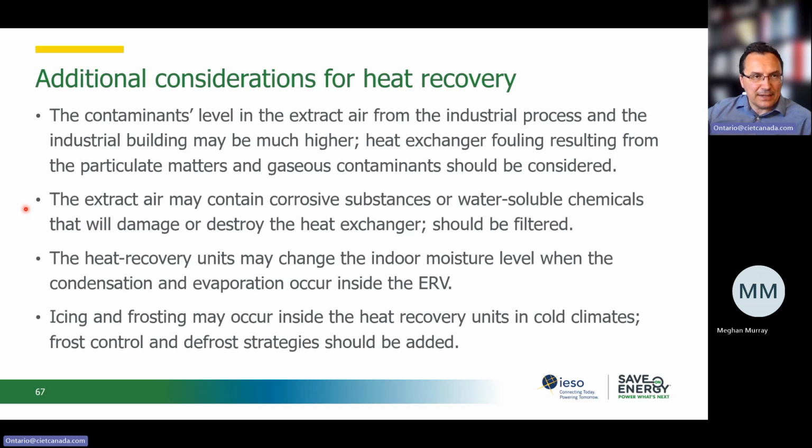So this extract air may contain corrosive substances, chemicals that can dissolve in water. So we have to design the heat recovery system in such a way that the impact of these contaminants does not affect the performance of the heat recovery system.